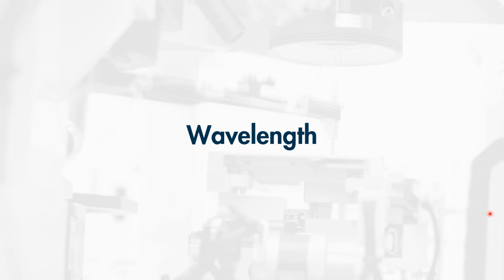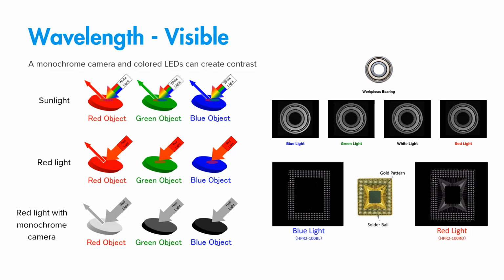So next we have to talk about the wavelength of the light and how we can use this to solve our applications. In the visible spectrum, we can use the wavelength of the light to essentially create more contrast. If you have sunlight shining down onto a sample, a red object will reflect red, a green object will absorb red, reflect green, blue absorb red, reflect blue.